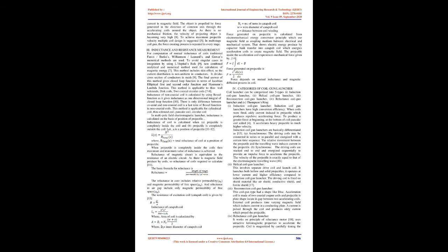The coil-gun launchers have a series of solenoid coils which accelerate the projecting object placed inside the coils. These coils use electromagnets in the configuration of a linear motor to accelerate a projecting object. The object and coils are arranged on a common axis. The capacitor bank delivers large electric current to produce the strong magnetic field essential for acceleration of the projecting object. The capacitor bank delivers a high current pulse given to the excitation coil.